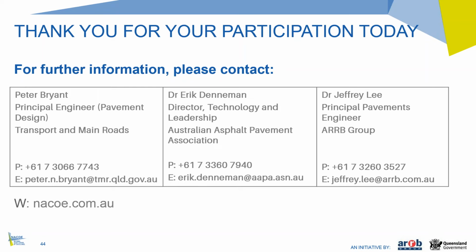For other construct-only type contracts, normally where the design's done separately and then that project goes out to tender, there's normally the opportunity for the contractor to submit an alternative tender. So in that case I would see that the designs would be done using the presumptive values. The contractor bidding for that work, if they so choose, could propose an alternative tender, or they could negotiate even after they've won the job to optimise the designs during the actual construction stage. That's often done for other changes, things like subgrade CBR testing, which will change the pavement thickness as well. Those sorts of changes are already made, and I really see this as being no different to that case.